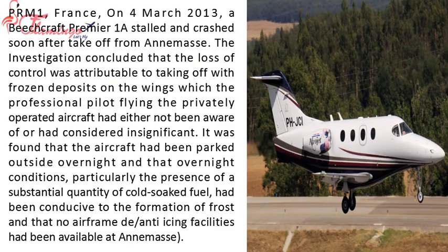PRM-1, France. On the 4th of March 2013, a Beechcraft Premier 1A stalled and crashed soon after takeoff from Annemasse. The investigation concluded that the loss of control was attributable to taking off with frozen deposits on the wings, which the professional pilot flying the privately operated aircraft had either not been aware of or had considered insignificant.